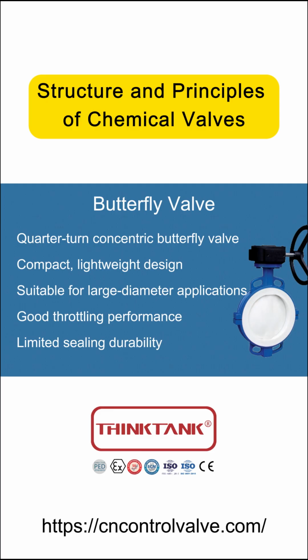The fourth type is the butterfly valve. It uses a central circular disc that rotates with the stem to open and close the fluid channel. Butterfly valves have a simple structure, are small, lightweight, can have a large diameter, and operate quickly and flexibly. A standard butterfly valve can achieve a good seal under low to medium pressure. Compared to the other three types of valves, its sealing stability and durability are slightly worse, but its regulating performance is better.